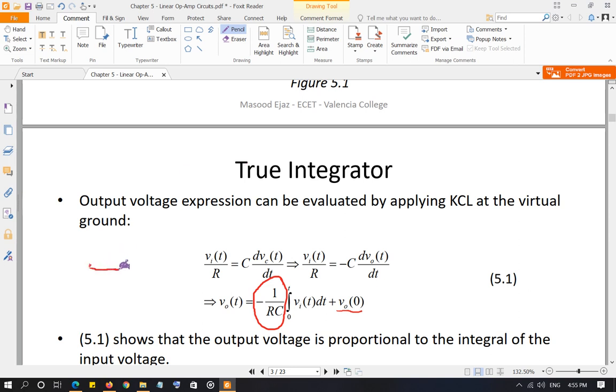What's going to happen is that voltage over time is going to start accumulating at the output, and the output will start rising with a specific slope towards the maximum value, which in this case is 15 volt if you're taking 15 volt biasing, or whatever the saturation voltage is. So it's going to hit 15 volt and then it's going to become constant because it cannot exceed 15 volt or whatever the saturation voltage is. So this phenomenon you can even observe in the simulation.